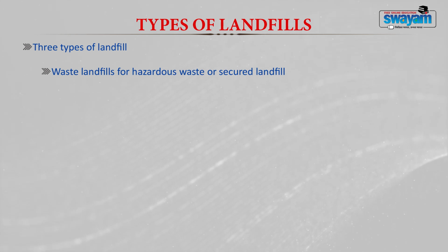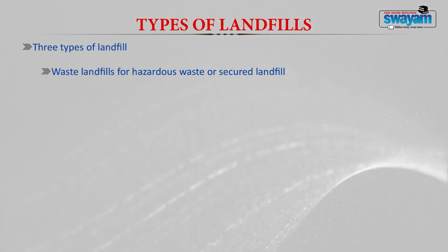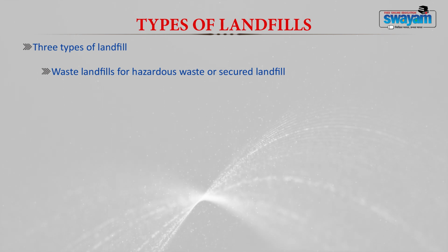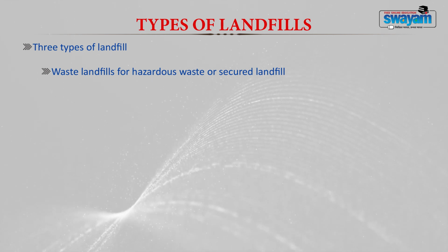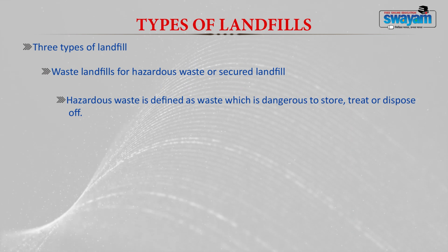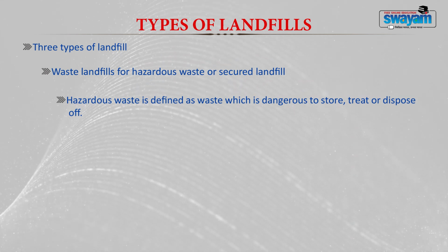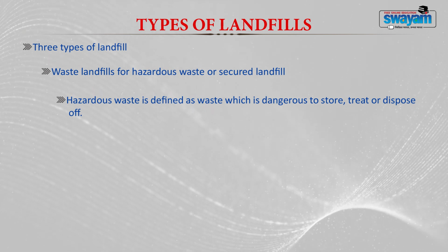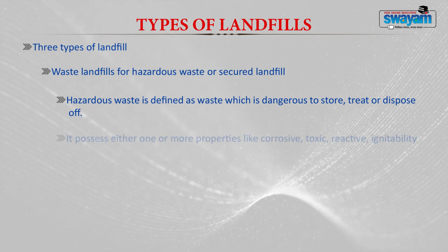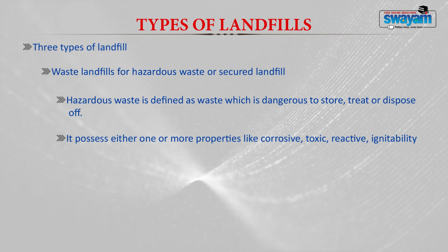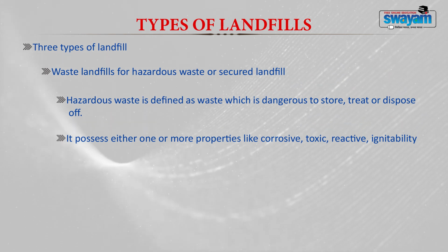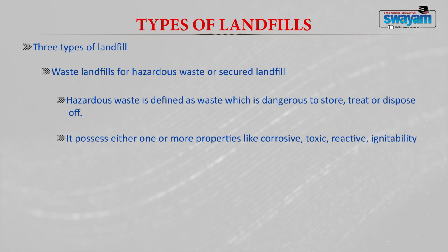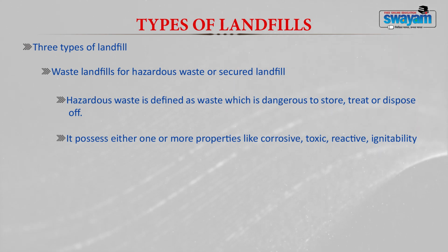So, now let us discuss briefly these types of landfill. The first one is the secured landfill. As I told you earlier, secured landfills are for hazardous waste. Hazardous wastes are generally dangerous materials which require safe storage, treatment and disposal. They have four major characteristics: corrosivity, toxicity, reactivity and ignitability. Accordingly, they have to be contained in a safe manner.